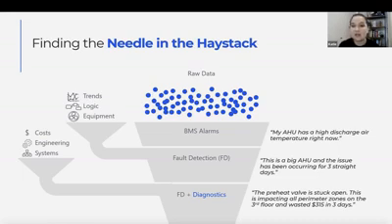Your FDD system knows that information in real time, and it also knows the type of equipment you have. So instead of just telling you your air handler has a high discharge air temperature, it tells you the air handler has a problem that's been occurring for 3 straight days, and it's a big air handler, so it's one you might want to pay attention to.